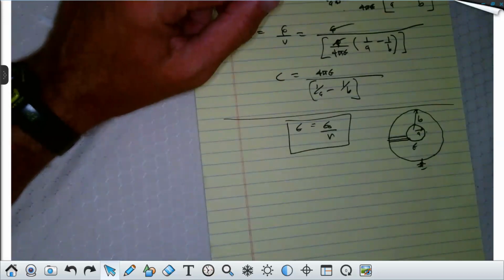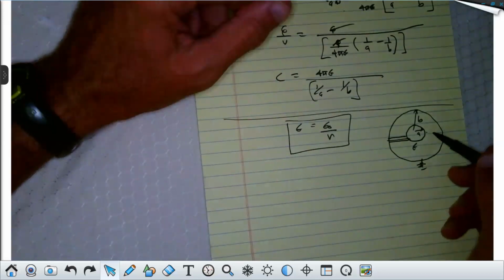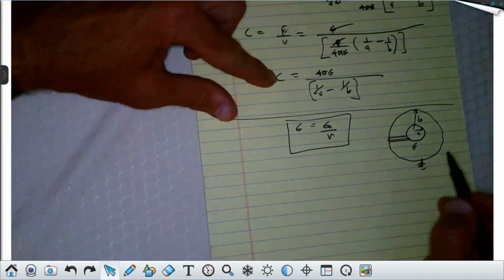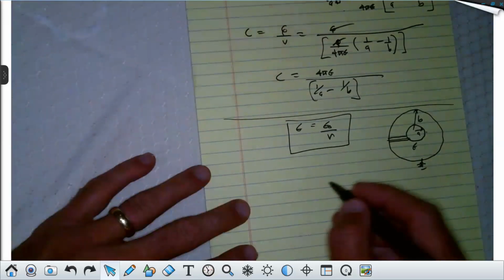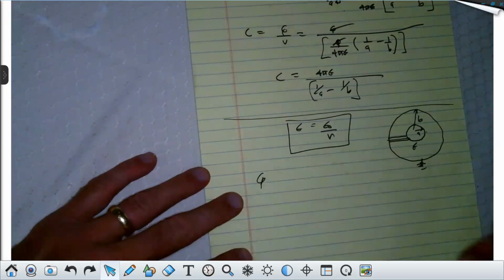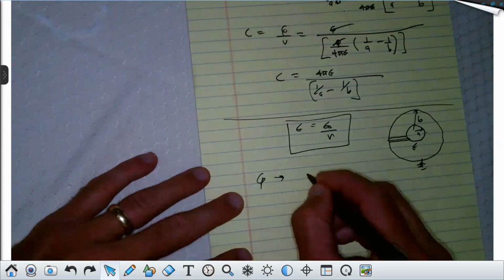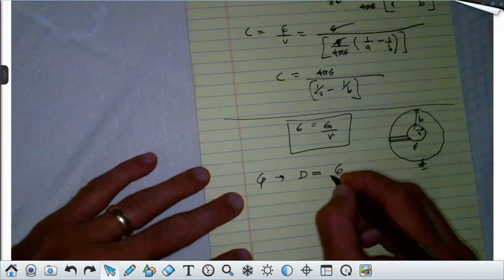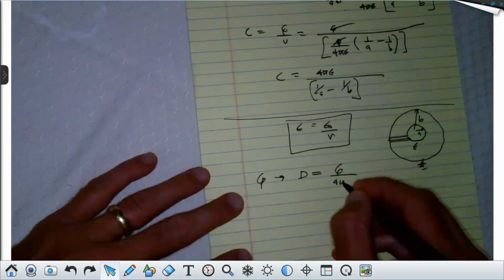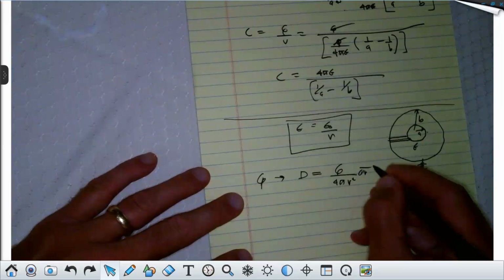So next, I'm going to go ahead and calculate the capacitance of this. Here, epsilon is not a constant, so follow me. First thing is I assume Q, right? Whatever it is, it's going to cancel anyway. Then I get the D field. D field's the same, right? D field isn't a function of epsilon. It's just Q over 4 pi R squared AR. Everybody agree with that?